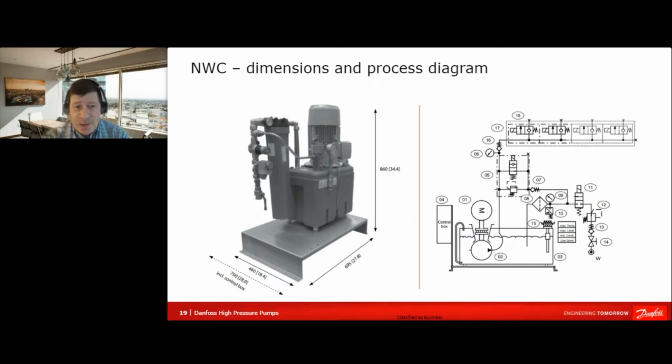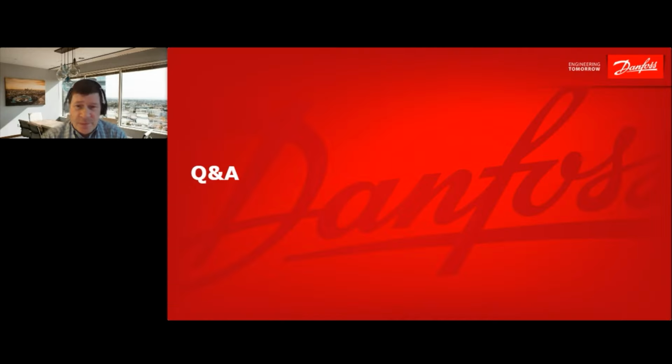But then the system must be so clever that you don't spray at the same time for all kilns. It seems to be rather typical that the moisturizing is needed in different drying kilns at different times. So you can divide the water spray to different drying kilns by using these VDHT valves. It depends on how many drying kilns you have, but roughly 5 to max 7.